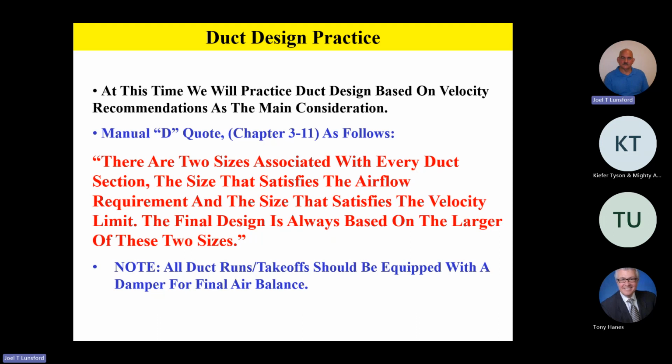And as you saw yesterday, we have methodology of actually knowing how much CFM is moving through a duct system, either with a rotating vane tool that we talked about or a hot wire anemometer, as we start commissioning our duct systems for proper airflow.